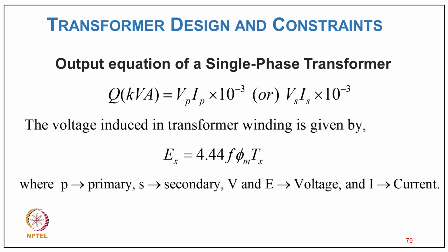The reason being that you don't know the power factor of the load by which the transformer can be loaded. It can be loaded only by a reactive load, maybe only by a capacitor bank, or by reactors, or by an active load like motors or others. So that's the reason: we don't know the nature of the load by which the transformer is loaded. That's why we rate it in terms of VA, kVA or MVA.